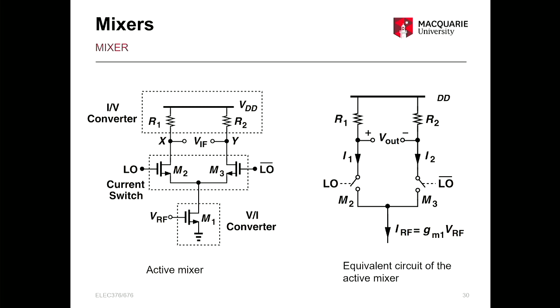For this circuit with the capacitor and inductor in parallel, I know that if these two values are the same, the parallel impedance will go to infinity. Yes, when the impedance is high, the voltage you get here is quite high, right?